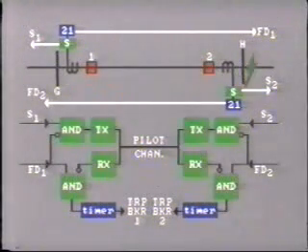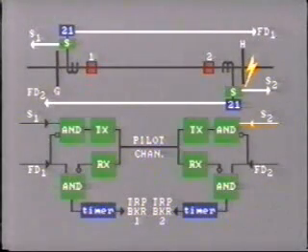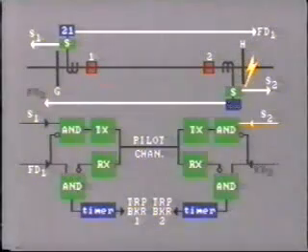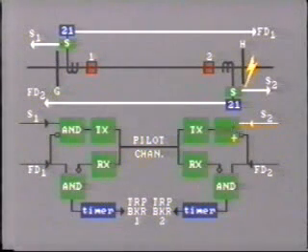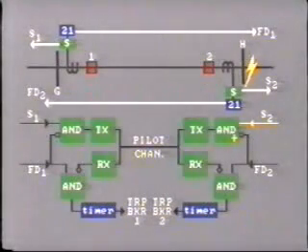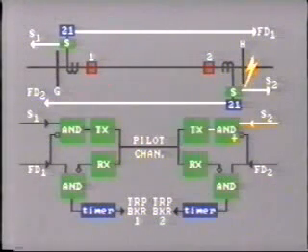Now, the logic diagram. When the external fault comes on, the starter relay at station H operates and sends a positive signal to the AND box. However, fault detector 2 has not operated, so it is not sending out a positive signal. Note on the diagram the 0 number at this input. Convention tells us that the logic circuit reverses the signal. That is, a 0 input signal reverses and becomes a positive signal. As this logic box shows, it requires 2 positive input signals, one from the fault detector and one from the starter relay. With these 2 positive signals, it initiates transmission of the blocking signal.